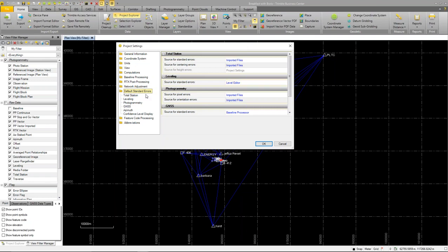Okay, so if you have a site calibration performed in TBC and you're doing a network adjustment, you will see a message that the site calibration is going to be removed, or same if there is a network adjustment and you're performing site calibration, you get a message asking if you want to clear the adjustment. Exactly. So it will tell you that you can't have them both, and which do you want to do? Okay. So, all right. So I'll get a little bit more into the parameters. I'm glad we conquered that now, because it makes the discussion easier later when we actually start calculating those parameters.